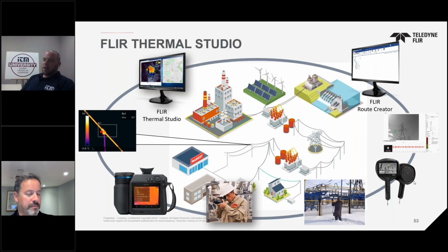So that's great. Another question that we had was when comparing noisy areas to less noisy areas. We'll just use the example. Is there any filtering mechanism that the SI-124 has to filter out noisier areas? Right. Typically in the outside environment, there are fewer ultrasound frequencies, depending on what you're looking at and the installation, versus inside, where there's a lot more echoing going on. But the camera's AI technology and the way it's designed, it recognizes the sounds or the frequencies, so it knows how to ignore them. There are filtering capabilities in the camera, and it's pretty much automatic. Honestly, there's not much you typically need to adjust for.